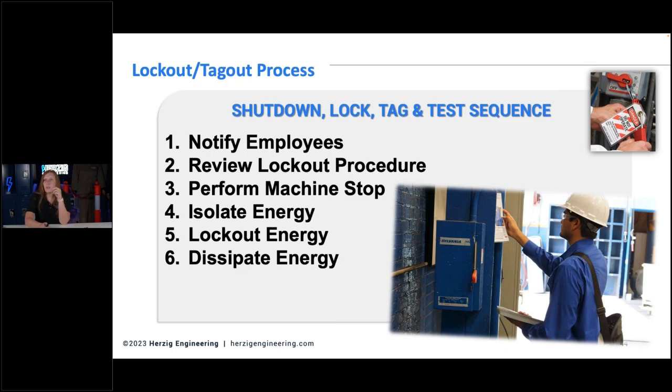Dissipate the energy. So it could be capacitors. You need a grounding strap for capacitors. It could be that you have to slowly open a valve that has pressurized air or something like that.